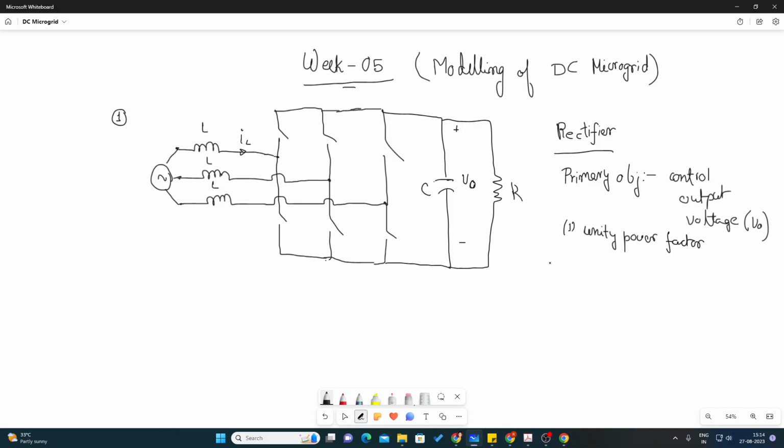There is no dynamics, just the DC gain of the transfer function. If the inner loop is faster, we can essentially say that the inner loop can be replaced with its DC gain when we are analyzing the outer loop.